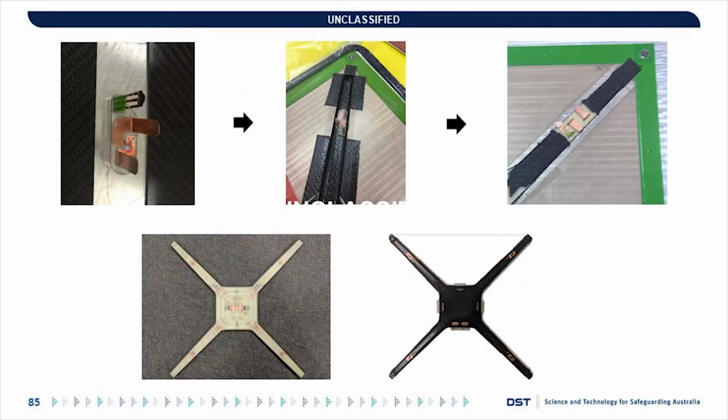So we developed a drone body last year, which had fiberglass pieces running through the center with sewn-in copper circuitry. If you look in the top row of pictures, there's a copper piece which, when you post-cure and flip that over, looks like what's on the bottom right, and you have an exposed copper pad which you can connect to. Through the middle, which is unseen after the cure, that copper pad protrudes into those fiberglass pieces and folds onto the circuitry so that you have a complete circuit running throughout the body of the drone.